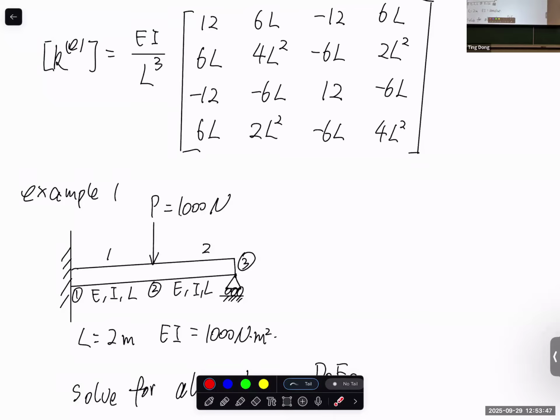And then you need to calculate, okay, what's the maximum stress, what's the maximum deflection at the wingtip, and can your wing box or wing spar structure survive this lift, or if the deflection at the wingtip exceeds your constraint or expectation, you need to do all the calculations. So my question is that there are uniform distributed forces, or elliptical distributed forces. How to put those forces into KQ equal to F?